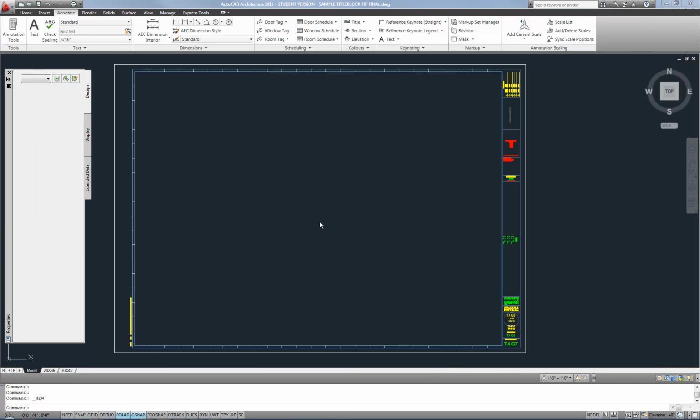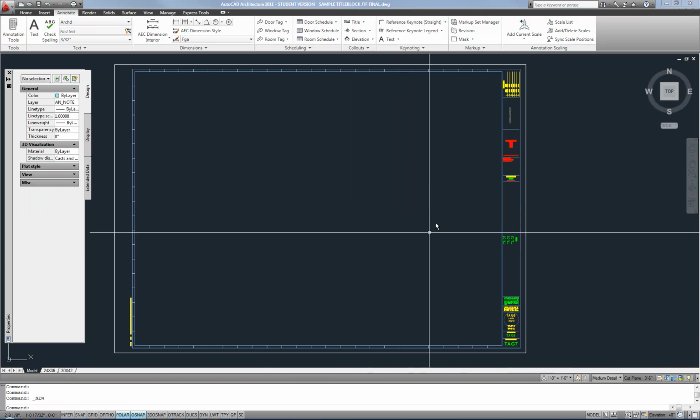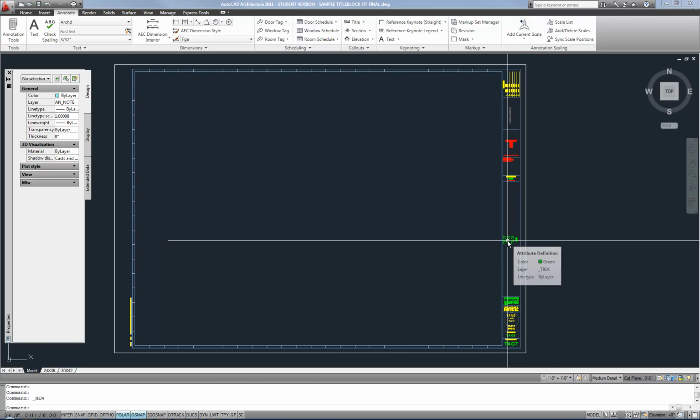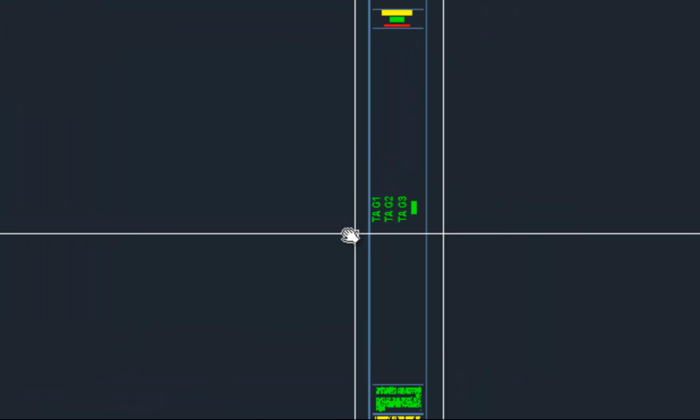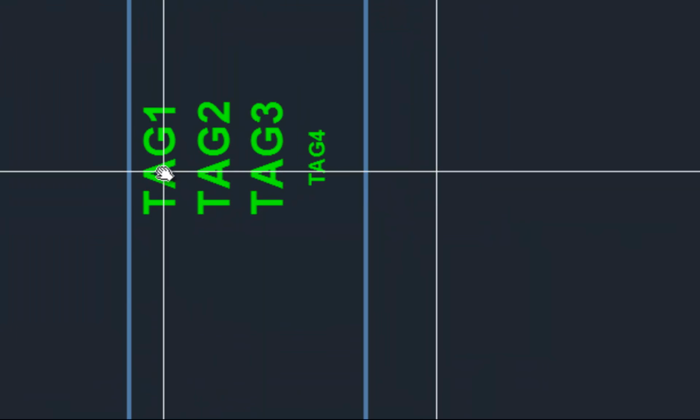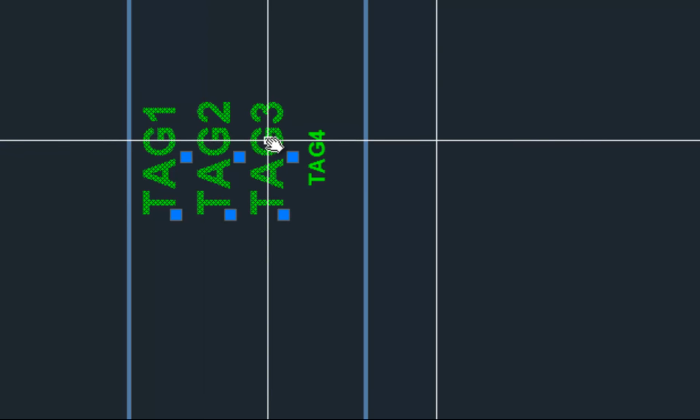When you make the block originally, you would have to specifically select these attributes in the order that you want them to show in the attribute manager. So if I was making this into a block here, I would have to pick these objects in this particular order in order to have them show in the order that I wanted when somebody's editing the block.